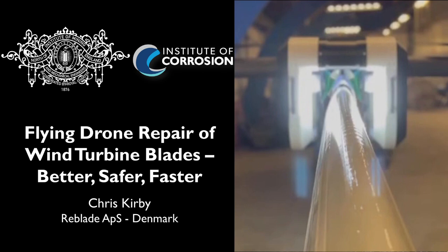Oh yeah, you're limited for sure. But we're designing the drone to be safe to operate in 14 meters per second. Normally you wouldn't allow a person to dangle from a rope much beyond 10, so that's why the weather window's a bit bigger. Obviously, you still need all the other conditions to be good enough to apply a coating. And if the wind picks up, the drone will automatically abort. It will just fly off and return back to base.